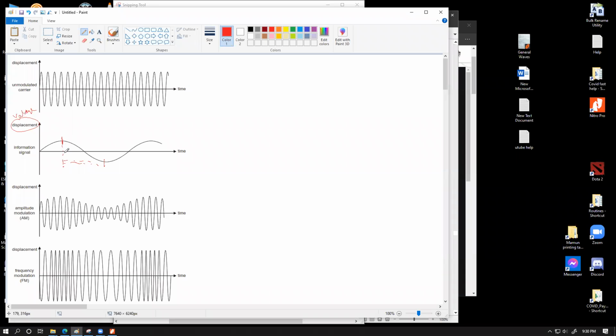So what I want you to understand is that over this amount of time, the voltage of the information signal will vary from this positive value to this negative value. In the modulated signal, this same information will be translated into, from this part, if I go vertically down, not perfectly drawn, but bear with me, this amount of variation of voltage of the information signal is represented by this amount of amplitude change within the modulated signal. This is never becoming 0, important bit. But this thing is changing from positive to negative.